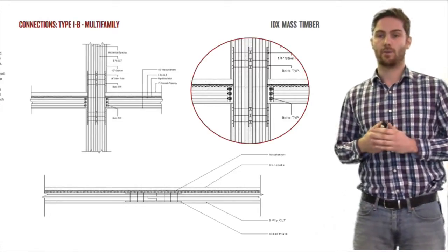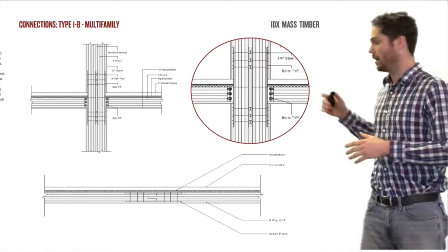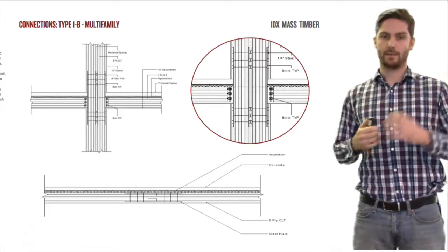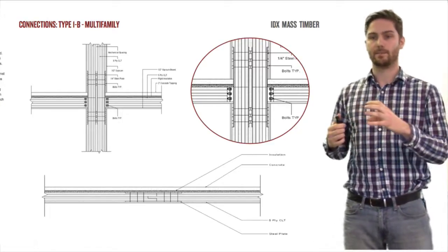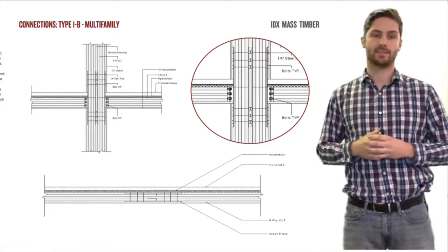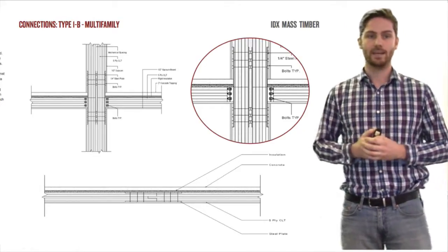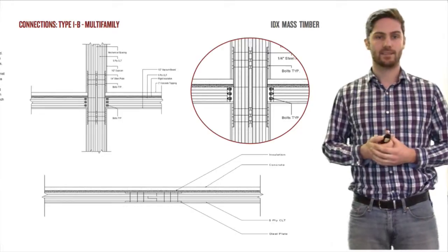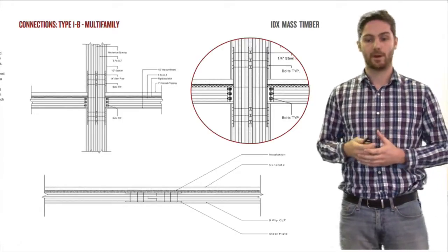And so here, for the diaphragms, you can see right in here that the diaphragms have a metal plate that is attached to the end of it, and those are going to then come in and attach to the metal plate that's attached to the CLT wall. And so that's going to be connected via bolts, and then the span for the CLT diaphragm is going to be the same with the composite action.